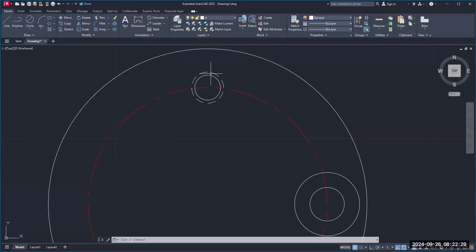Yes. All right, I'm going to erase this. Everyone else just stay where you're at. I'm going to erase this circle, right? I'm going to go to circle, center diameter. I'm going to come in and see it's going to automatically pick up that center, click. I'm going to drag it out to 0.25, enter.